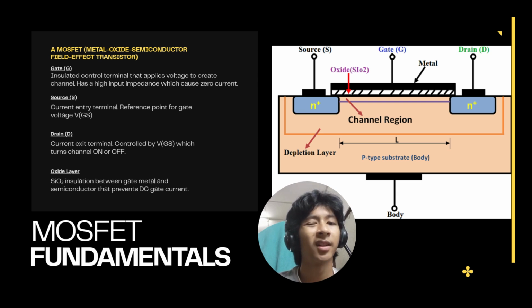So how exactly are we going to get it to connect? Well, there comes the gate. The gate is made out of an oxide layer. There is a silicon dioxide insulator between the gate metal and the semiconductor. And why so? This is to prevent any DC current. And why do we want to prevent it? As I mentioned earlier, to prevent any noise.